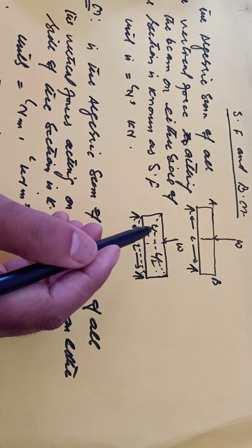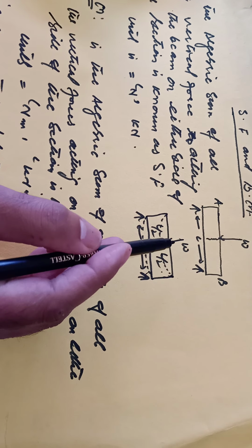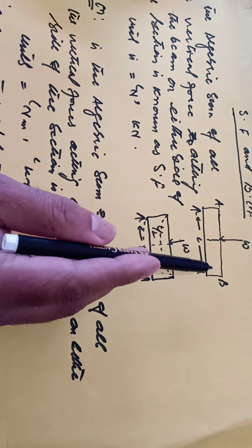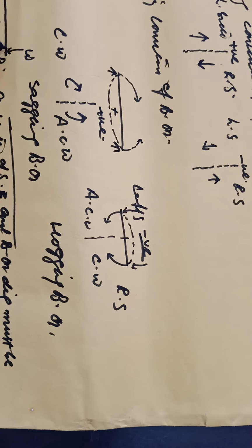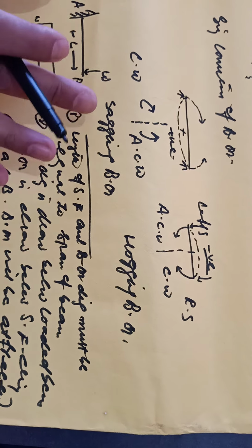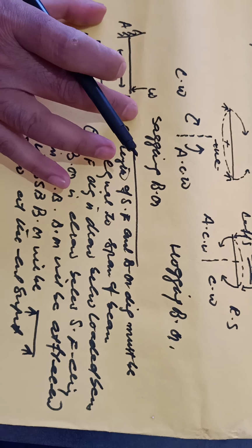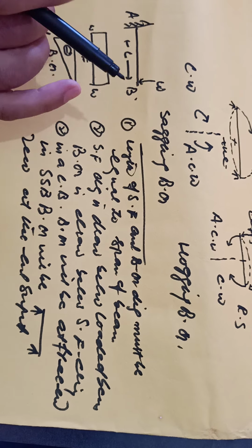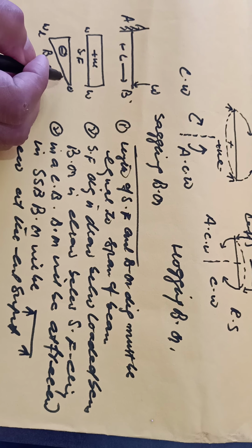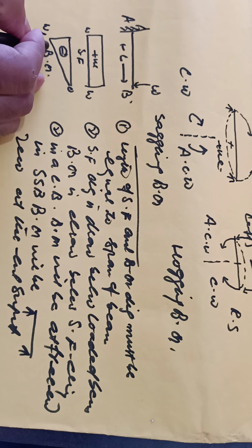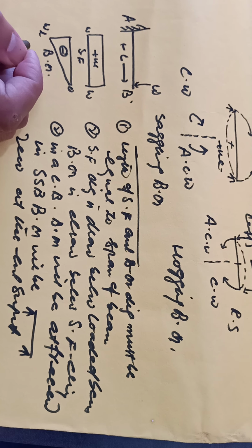If no load is present between 2 points, shear force will be constant, but the bending moment will be in an inclined direction.